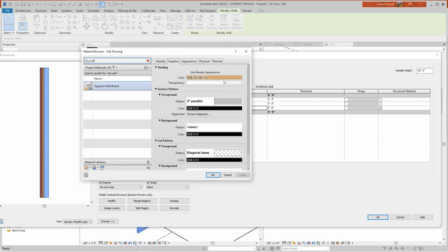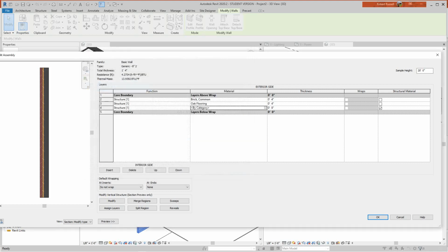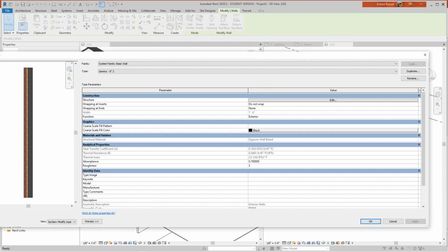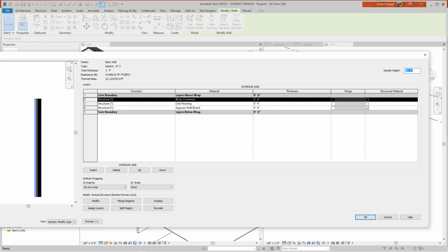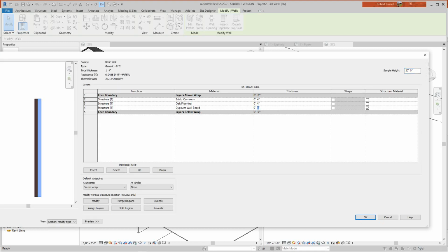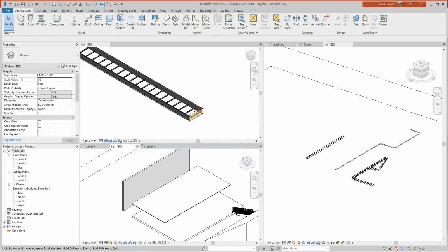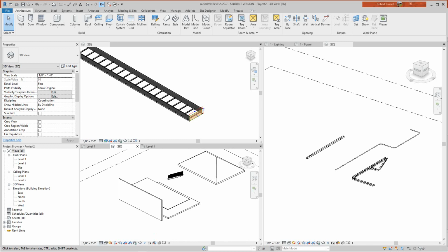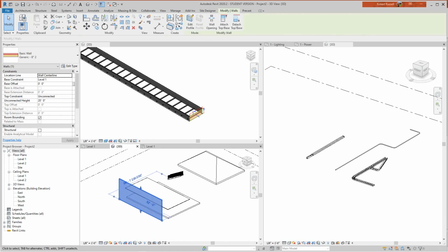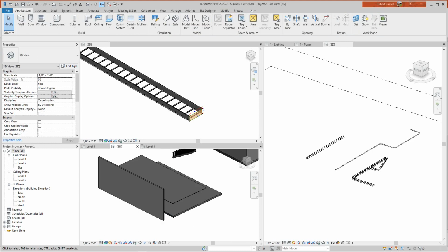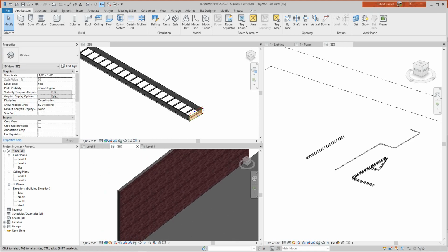So this is what system families are basically what you use to do with them. They're basically there to, okay. And so there's the wall. Now that gypsum board shouldn't be that thick. So I'll go back in my edit and see that's 8 inches. I just want to make that say a 1/2 inch. Okay. And then if we go here to our model, there's the wall. So I'll make this, let me see if it's realistic here. Okay, what happened? Oh, there it is. So there's our wall we just created.